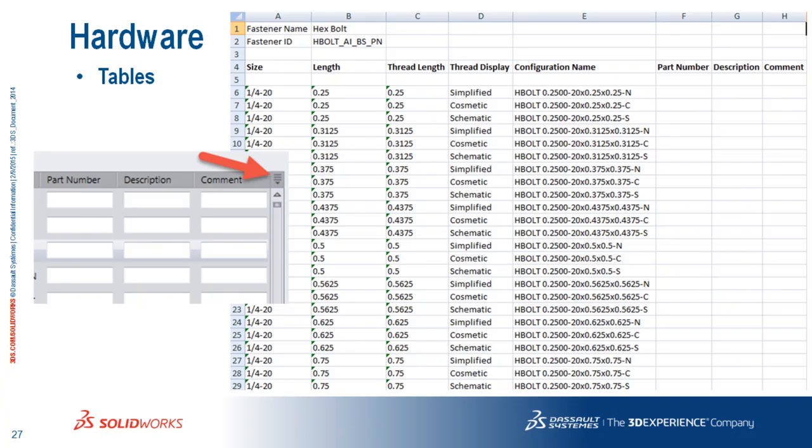This means instead of going tab, tab, tab through each of those little property boxes, you can spit it out to a spreadsheet, grab a whole section of stuff you don't want in your configuration list, delete it all out, add your custom properties, everything all in one shot, re-import it back into SOLIDWORKS, and it'll make the changes for you. Well, there's pretty much your customization right there. That thing alone there will save you time like you won't believe. Okay, just go in there and start configuring and messing around with those little check boxes and you'll be sick of that in a hurry.